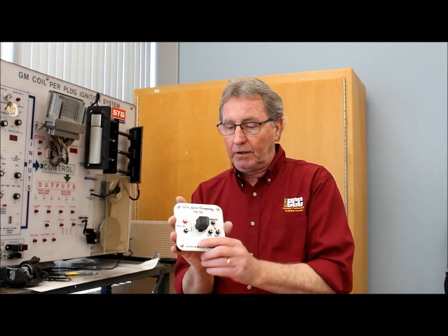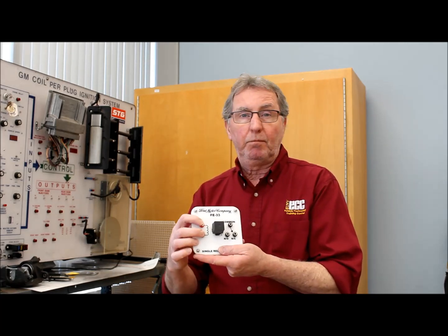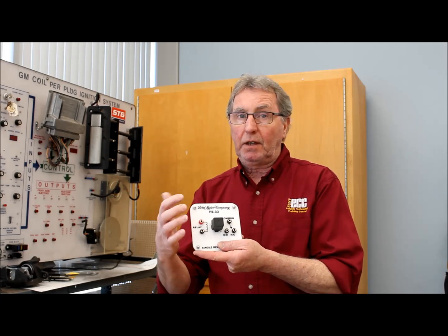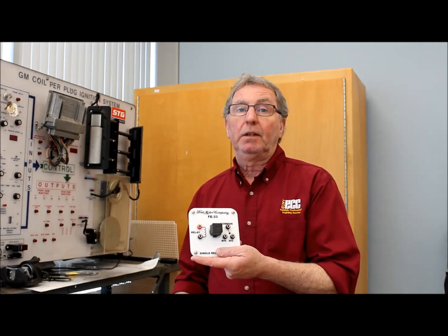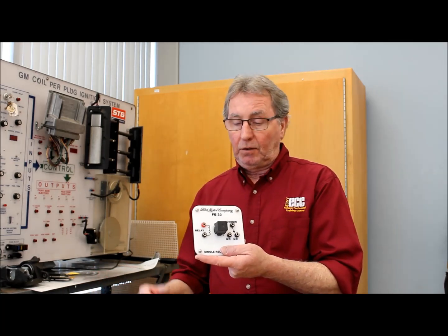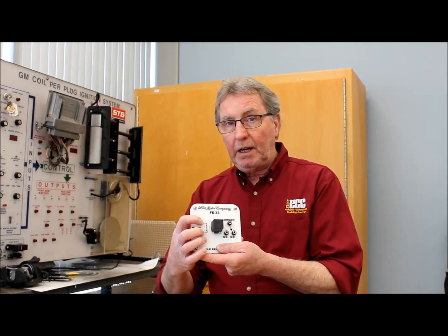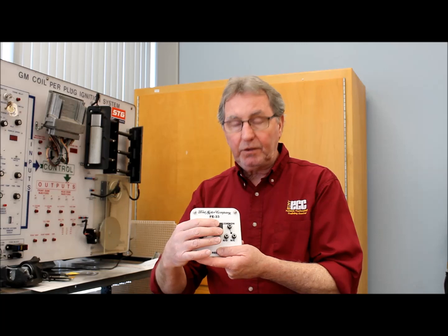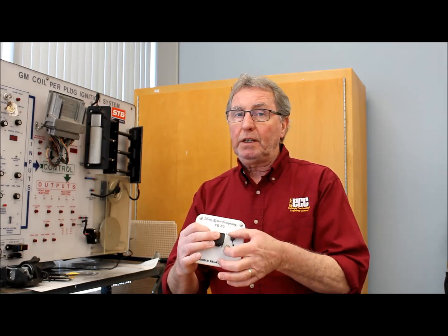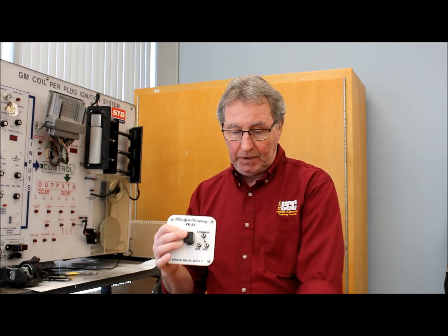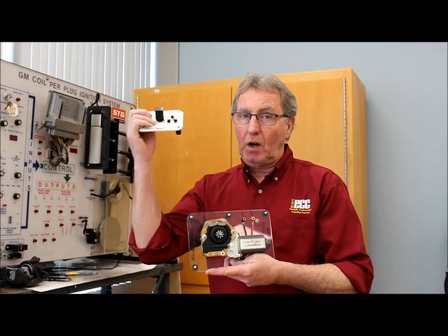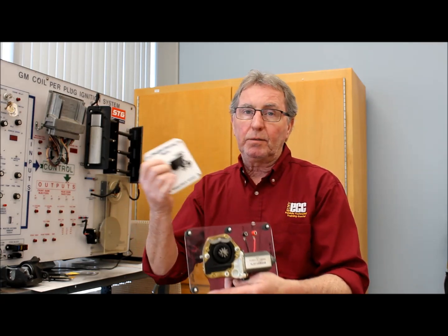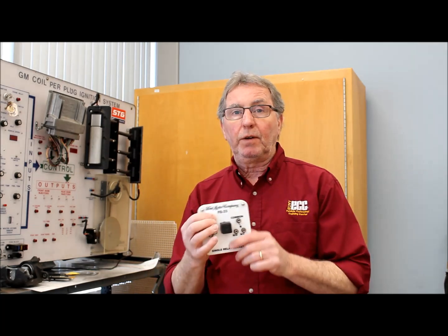And what the relay does, the relay, if you remember, was about 0.18 amps to operate the relay. Can the computer put out 0.18 amps? Yes, it can. So by putting out 0.18 amps, it closes the relay, which then supplies the current to the motor, and so we're using a small amount of current to control a large amount of current, and that's indirect control,